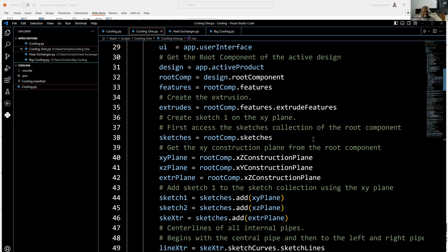But what is interesting here is the way I create my sketch planes. The 3 planes I'm creating here are planes that I plan to sketch on. This is one example where the API is different from the GUI I've been using. In the GUI, you want to sketch, you create a sketch plane, you use it, finish. You want to sketch again, you go again and create a sketch plane. But when you are programming, you can create all your sketch planes at the beginning, and then you can use them later on. The program doesn't have difficulty knowing what sketch plane to throw any graphic element you have onto. When you reference the sketch plane you have created, it will go and put it there.